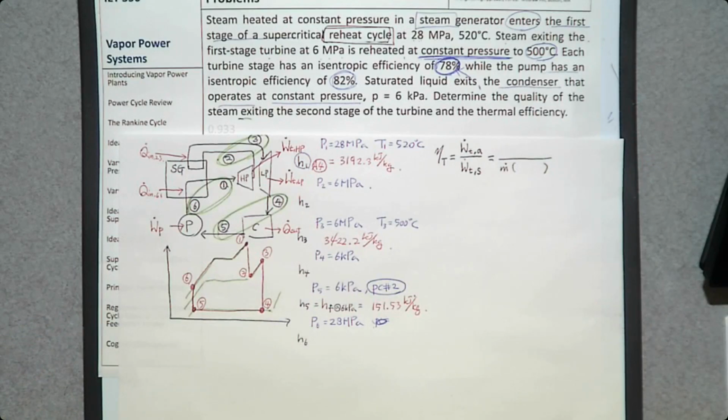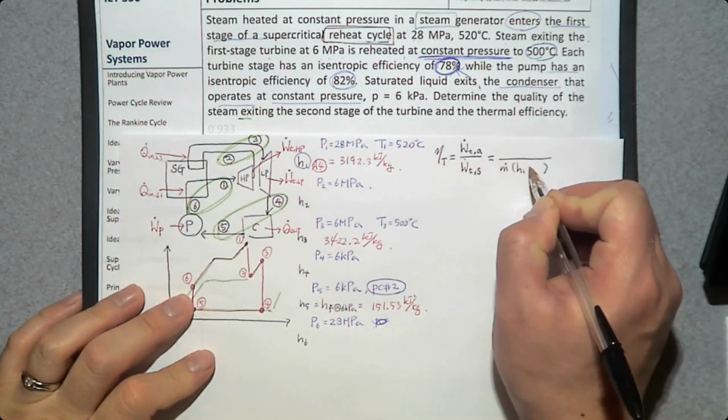H1 goes in, some of this H is going to be converted to power. Then what is left over is the reject that exits this high pressure turbine. So between H1 and H2, H1 should be greater than H2, right? Because the turbine power was a part of this H1, and that has been removed from the turbine, so only the leftover is going to be less than this one. So turbine power is going to be H1 minus H2.